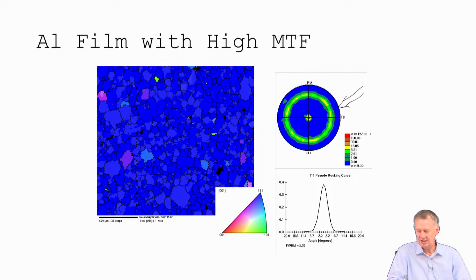This one, as you can see right here, if you can read that, it says 127 times random with the way we calculated that. Remember, the way we calculate it is either binning or through the generalized spherical harmonic expansion. So we say, okay, we have 127. If this was a completely random or uniform structure, this value would be 1 for how many blue grains we have, how many 111s are pointing straight up. We have 127 times random.